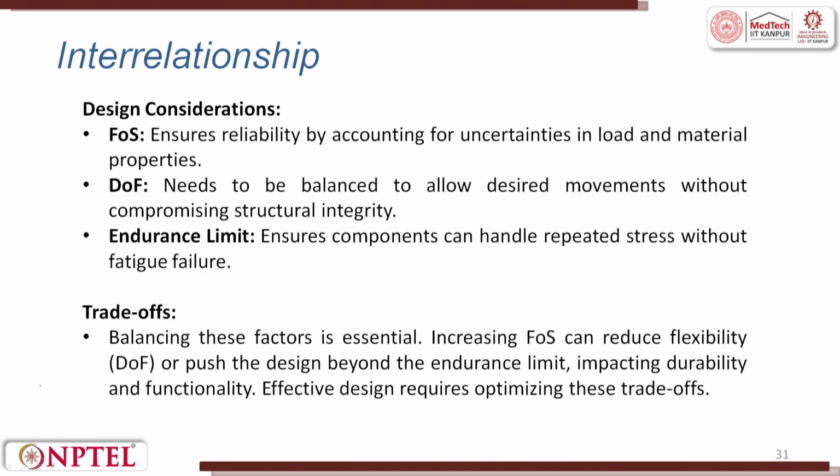So, in the design consideration, FOS ensures reliability by accounting for uncertainty in loading and material. DOF needs the balance of all allowed movement without compromising on structural integrity. Endurance limit ensures the component can handle repetitive stress without fatigue failure.